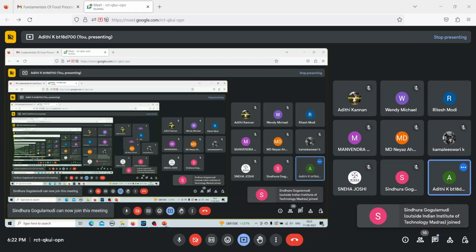Ma'am, we are adding all the values of L, ma'am? Yeah. Okay. Thank you. So delta T is constant, so you need not add it. You can take it out, but you have to add all the L values at each and every temperature. So the summation is basically equal to 7.94 into 10 power minus 8 plus 2.51 into 10 power minus 4 plus 0.025 plus 0.79 plus 0.05, which will give you 0.865. The F naught value is then equal to 4.325 minutes.